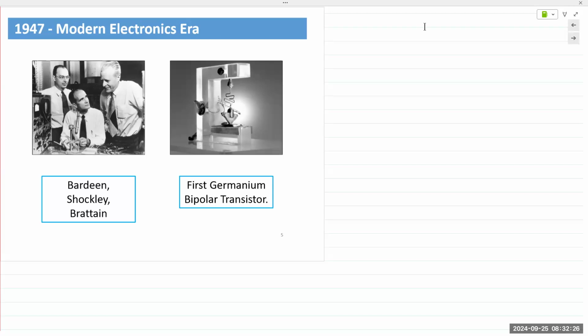To give you an idea of how clean it is, in a room like this, you have about 1 million or 2 million particles in a small cubic centimeter space, about the size of 0.5 microns or smaller. In a clean room, depending on the classification, it'd be less than 10. Modern day clean rooms, it's less than 1. So it's class 1, class 10, class 100, class 1000.